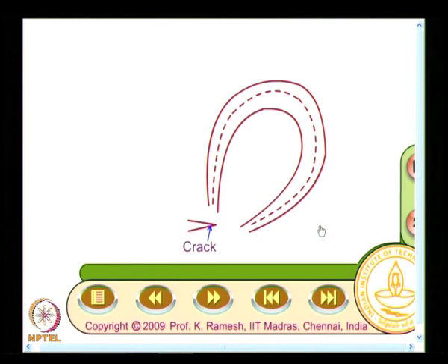What I need to do is take tangents and then draw the normals. So, I should scan for this portion only along this direction to pick out this point. For picking out this point, my scanning direction should be altered. So, the scanning direction changes as a function of the curvature of the fringe, which is very complex.